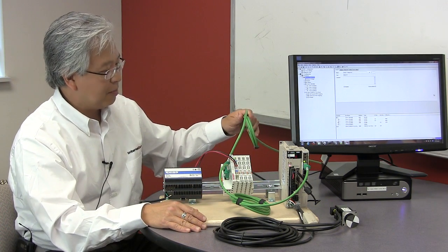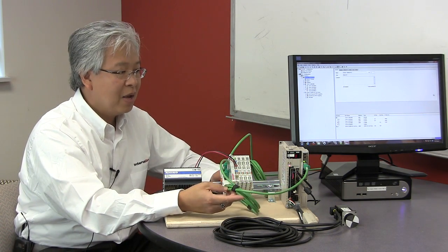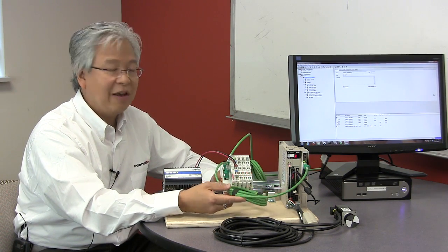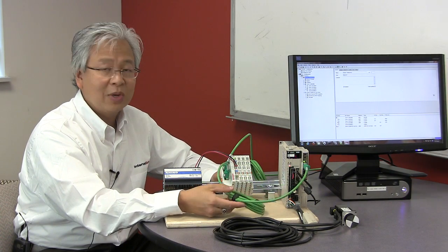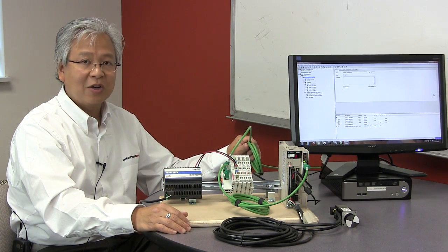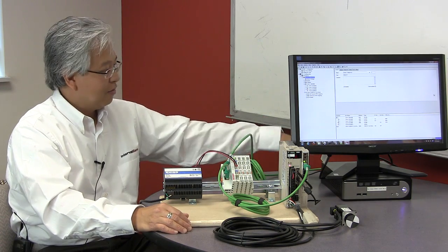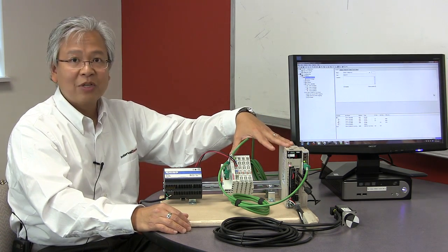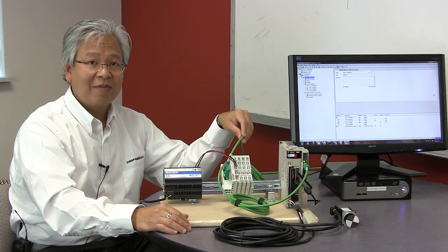One of the big benefits, not only with EtherCAT, is being able to use the standard Cat5, but one thing you should know is safety is integrated into this bus. Not only is this a fantastic real-time communications bus, but it's also a dedicated safety bus as well, because there are dedicated channels to pass the safety messages from your controller all the way down to your motors and slaves. Everything is integrated on a single Cat5 cable.